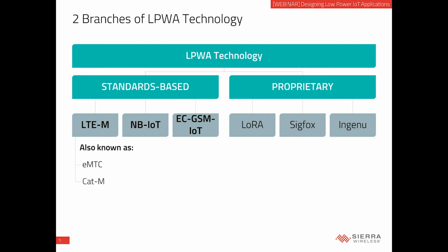These are the most famous ones. There are a number of them, but the most famous are certainly LoRa, LoRaWAN, Sigfox, and Ingenu, owner of the RPMA technology. The companies behind these technologies recognized very early on that there is a need for IoT solutions that, while still ensuring wide and deep coverage, reduce power consumption compared to your regular legacy cellular IoT solutions.